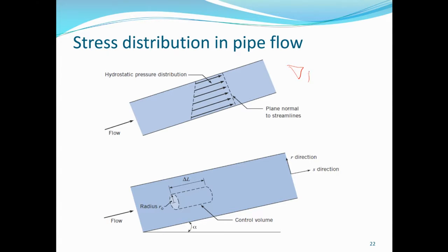The Euler's equation is delta p z, okay, minus delta p z equals rho a, okay, and the acceleration. So if the fluid is accelerating in this direction, it means the pressure gradient is increasing in the opposite direction. Okay, if it's accelerating in this direction, then it means the pressure is increasing in the opposite direction, meaning the pressure is decreasing in the direction of acceleration.